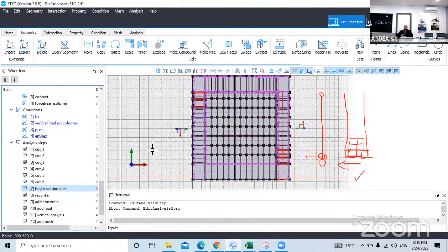So what we did is to create a script where the user basically can specify a set of nodes inside a 2D or 3D model. And this script is able to take the internal forces of the elements, and taking these internal forces, it will integrate them along this section in 2D or along a face in 3D, okay?